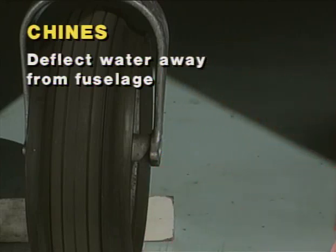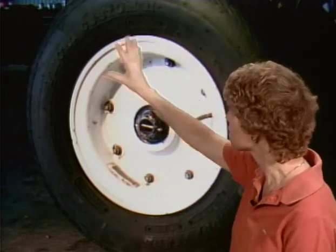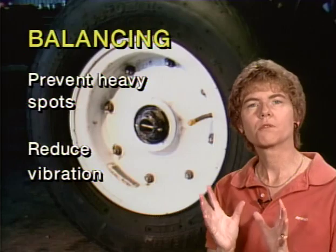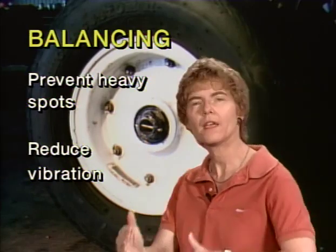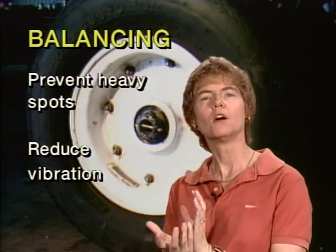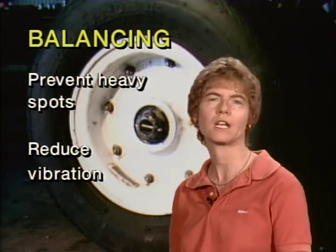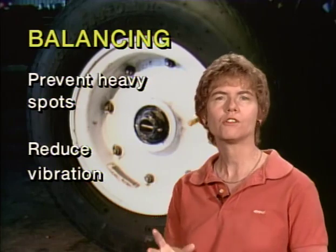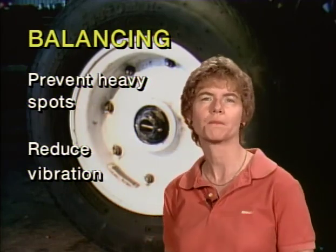Aircraft wheel assemblies are balanced, and the primary reason for balancing the aircraft wheel assembly is to prevent heavy spots and to reduce vibration. You want that tire to roll smoothly. You don't want to have a heavy spot where it always hangs in one position, and then when you land, you're always landing on the same spot. And you want to make sure that you don't have vibration on takeoff and landing.